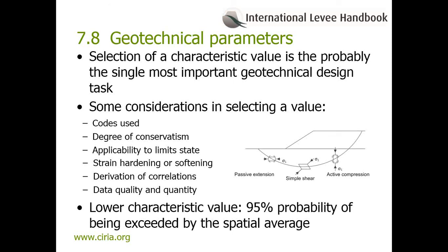Discussion is included on the selection and validation in the section on the validation and treatment of data outliers, and the need to consider the spatial distribution of the data to avoid overlooking localized areas of adverse ground that could impact on the performance of the levee.